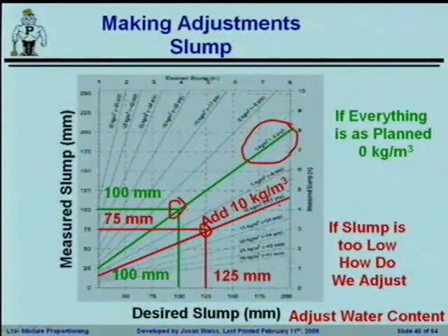Okay. All right, and next week we will use my favorite slide where I have used a standard 96-point font to tell us that indiscriminate additions of water should not be tolerated in the field. We do not want to be adding water in the field because we've redesigned the entire mix. This you're going to do at the step where you've done your mix design. You've gone to do your trial batch. You don't get the numbers you wanted to get, or you don't get the numbers you expected to get. How would you adjust it to redesign the mix, to redo a trial batch to make sure you're going to get the concrete that you're after?